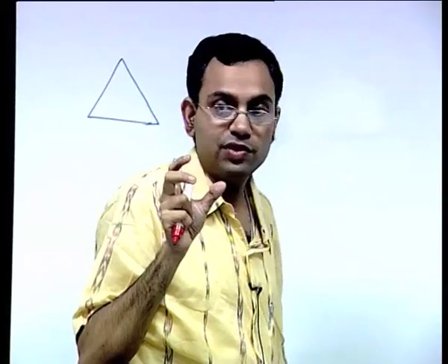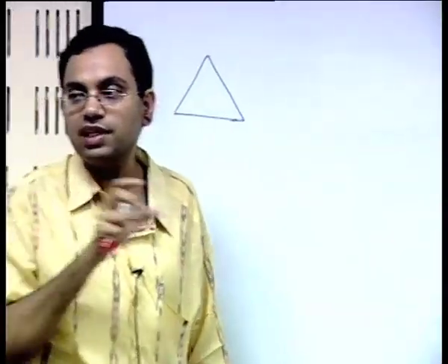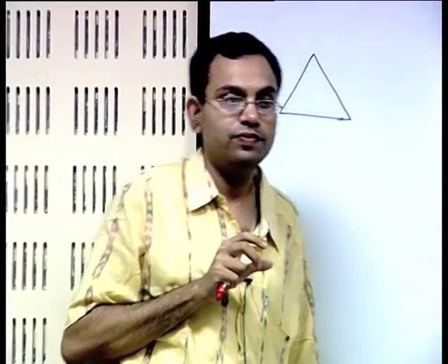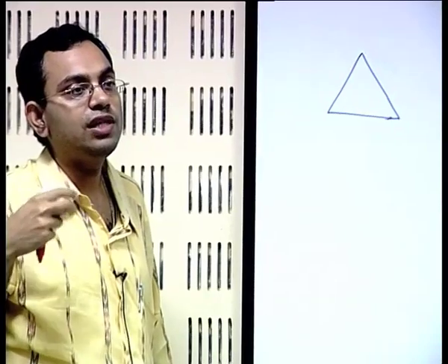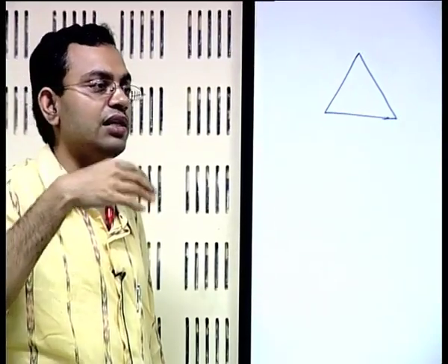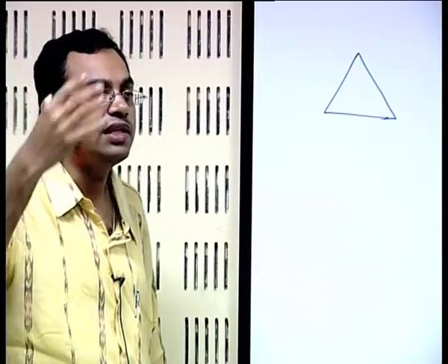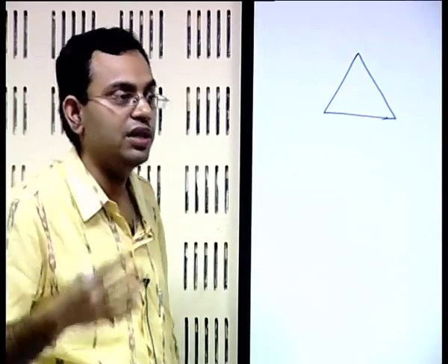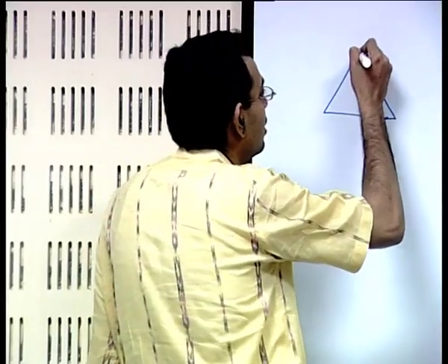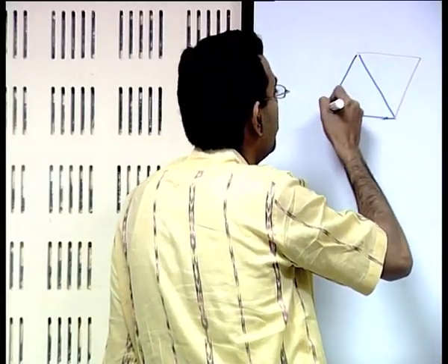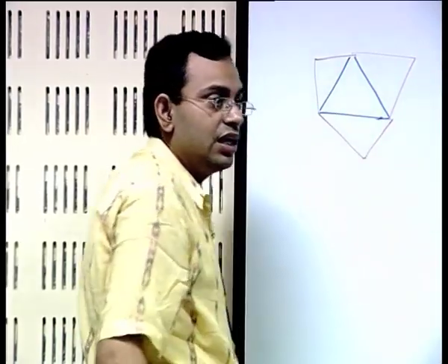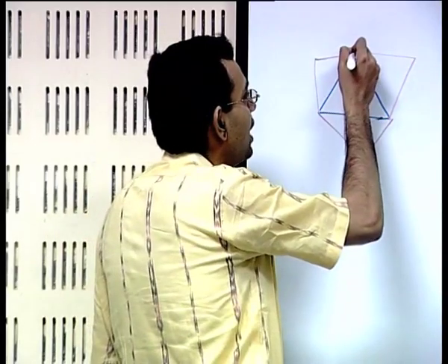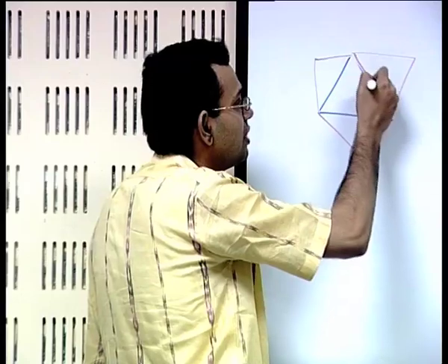Till now in structured grids we have considered rectangular control volumes. Instead of that, just consider that you have a triangular control volume. One control volume is influenced by whom? It is influenced by the transport phenomena occurring across its neighbors at the most, but not beyond that. So you can consider how many neighbors? You can consider 3 neighbors. Each neighbor is a triangle with base as one of the sides of the original triangle.